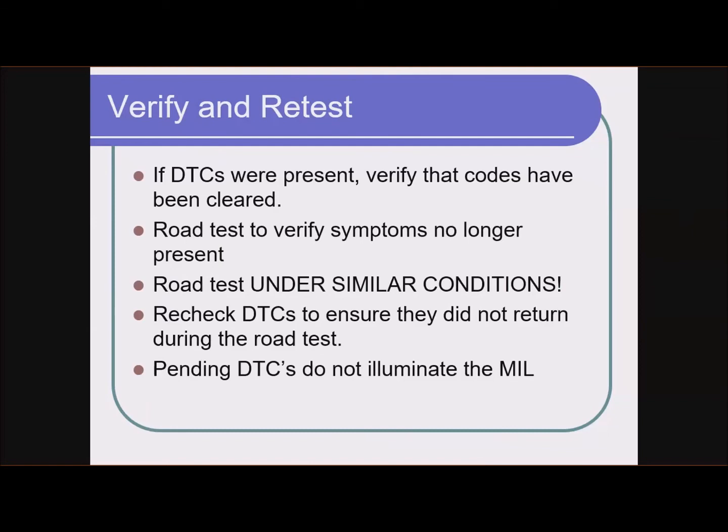But here's one caveat, one thing you have to keep in mind. Some symptoms only show up when the engine's cold. Some symptoms only show up under load. Some symptoms only show up when the engine's hot. Maybe on a cold day, maybe when it's raining out, I don't know.